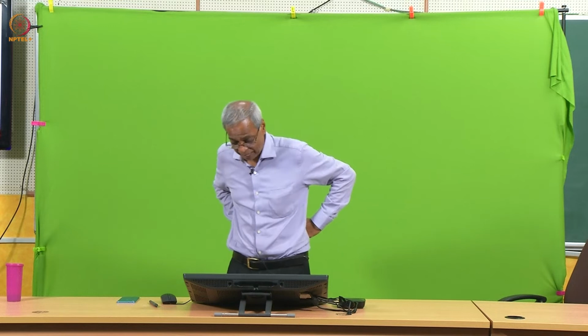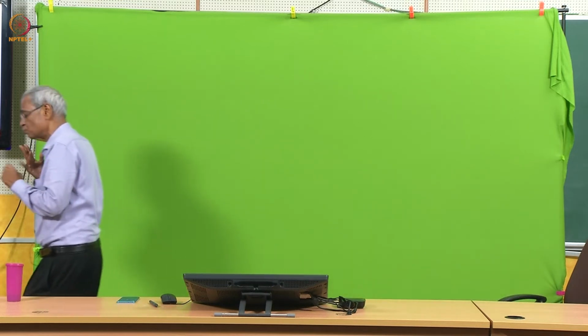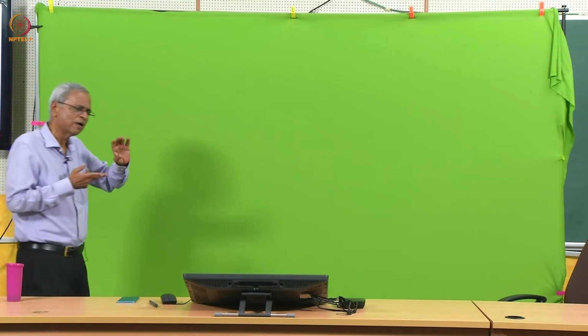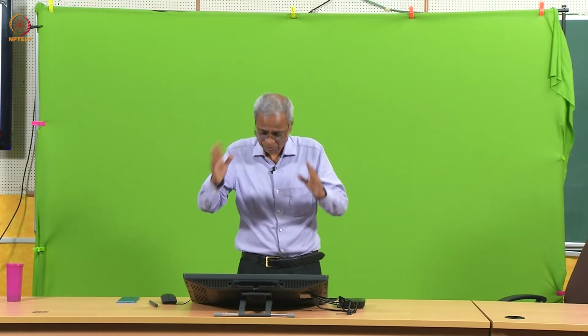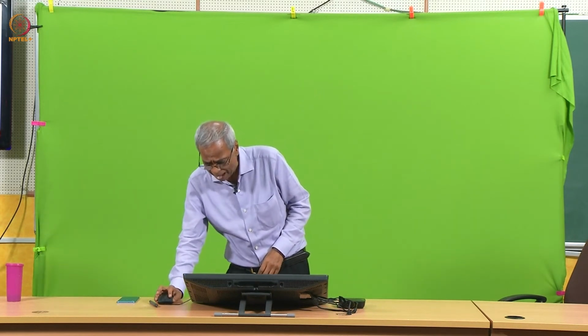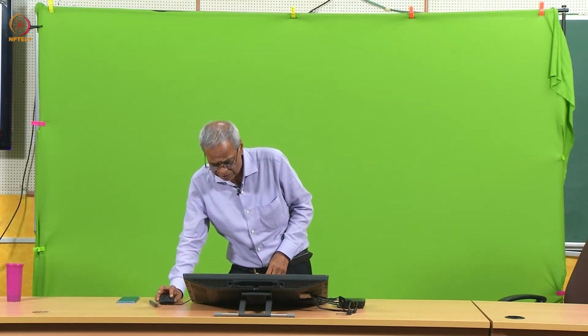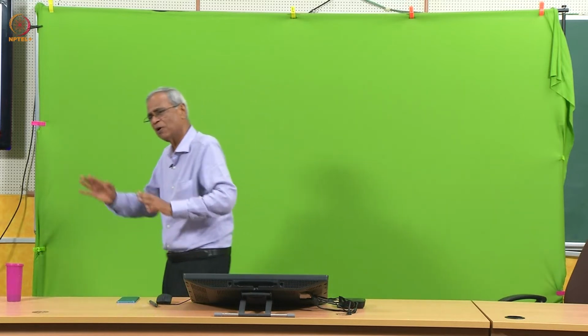And finally, the BMS, battery management system. Battery management system's task is twofold. We will get into details of that. First is protection, safety, second is cell balancing, because cells become imbalanced. Why it becomes so, we will look later on. So, cell to pack manufacturing we have to do as per Indian conditions, and this is a value add we can do today, and we are already doing it.